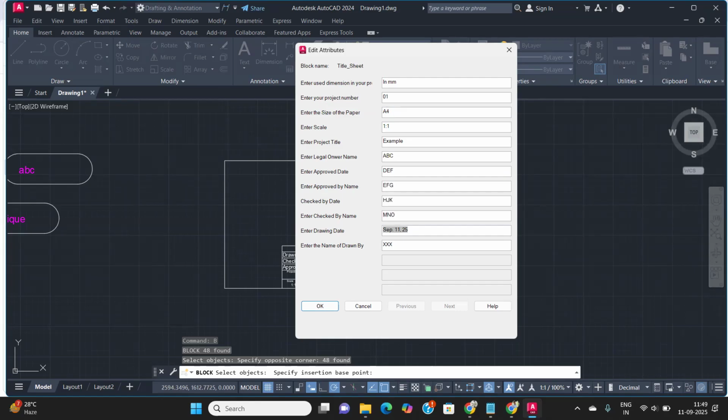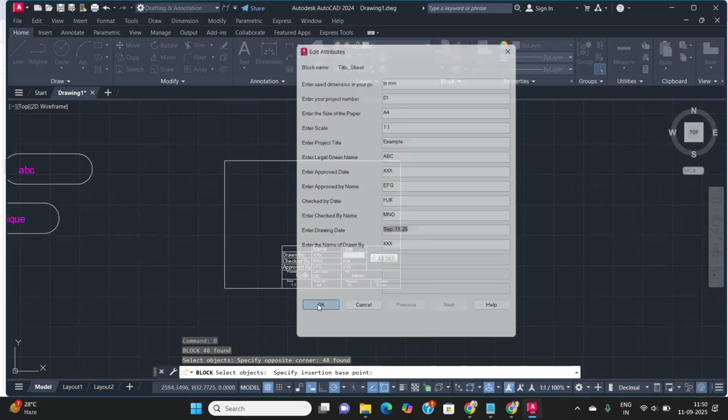And the date is right here, suppose today, any date you can write here. If you write nothing, then drawn by name, enter drawn date, whatever. Drawn date shows the current date, right? Where you create it here, this current date will be shown here. And then if you don't need it here, just click on accept and then click on OK. Okay. If you change it, then the value will be changed, and click on OK.